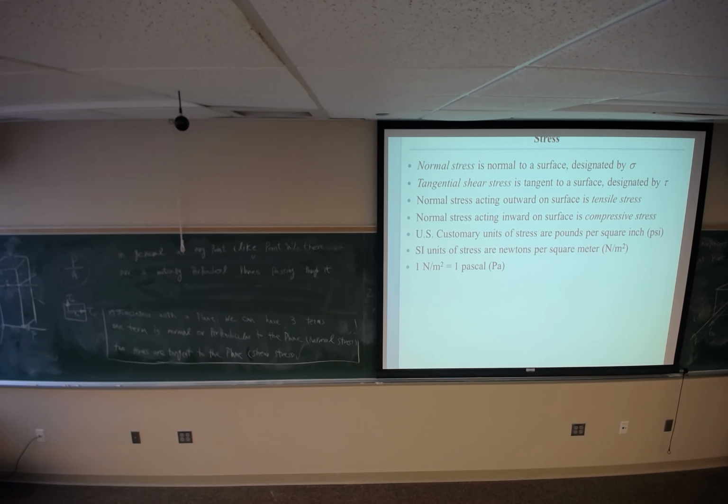This is going to be tau because it's shear stress. The first subscript is y. This shear stress is in x direction, so I label this x as the second subscript. And this one is going to be tau y, but the second subscript is in z direction. It's going to be tau yz.